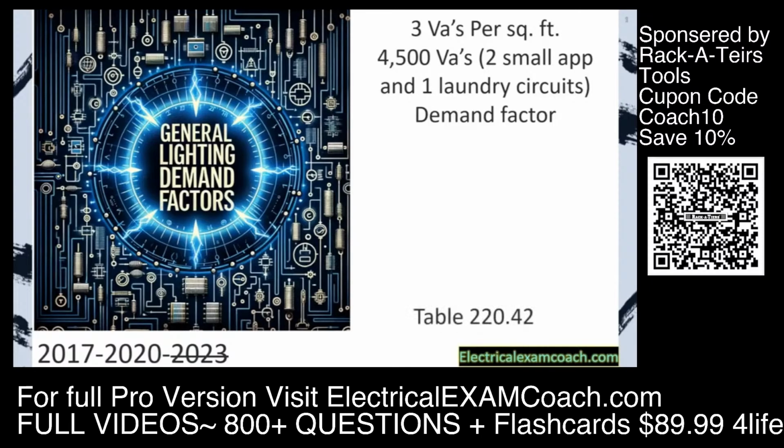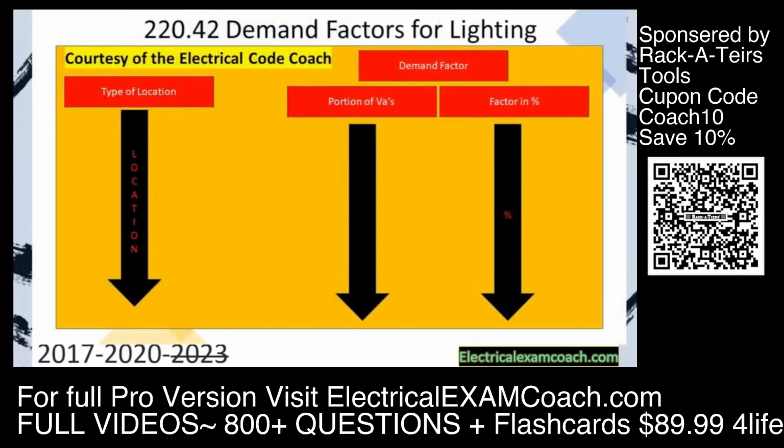And for this one, we're going to head to table 220.42. It's a very important table in our load calculation process. When we get to table 220.42, we always read the black bold heading to make sure that we're in the right table. And it says demand factors for lighting.